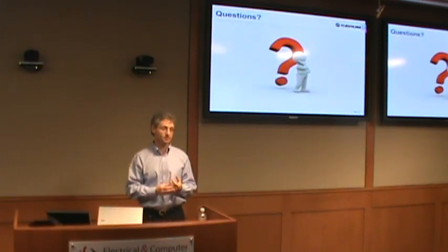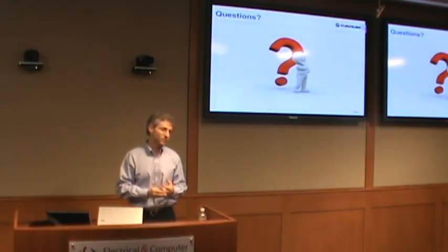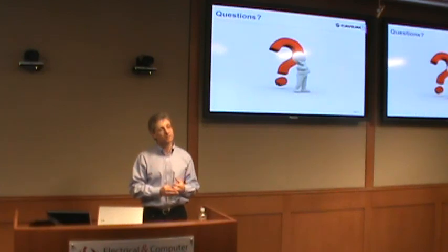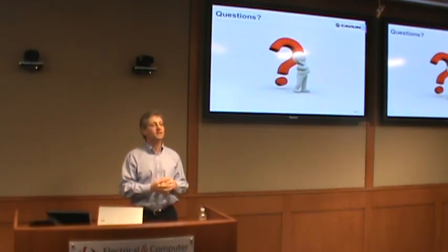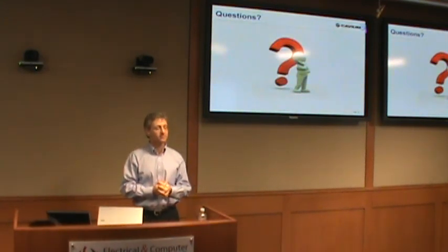So from the cache's point of view, it's like a scratch pad almost. You're saying it doesn't have to be coherent with memory. You can just throw away whatever. That's right. Do you have to lock it? So effectively, after the don't write back, we make the value of the cache block unpredictable until something writes the cache block again. Okay.